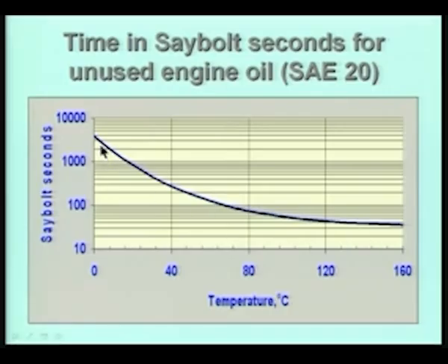The point I want to make here is that for most liquids whose viscosity we want to measure using the Saybolt viscometer, the drainage time is measurable, and very accurately measurable, because it varies from about 1000, 3000 to about 50 or 20, 25 or 30 seconds, which is easily and accurately measurable. That is a very important thing. In other words, it means that this Saybolt viscometer can be used for a large range of values of viscosity of the liquids.